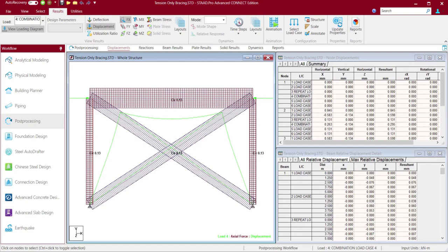But if you see it intuitively, just imagine what the response would be in the physical sense. Just imagine when both the loads are applied in the opposite directions having the same magnitude, then of course none of them is supposed to experience the tension. Both will undergo compression. But if you are doing the load combination and performing the analysis instead, then it is giving a very misleading result, right? It is showing that both the members are experiencing tension. So that's the fallacy of using the load combination because we are using it for the nonlinear case.